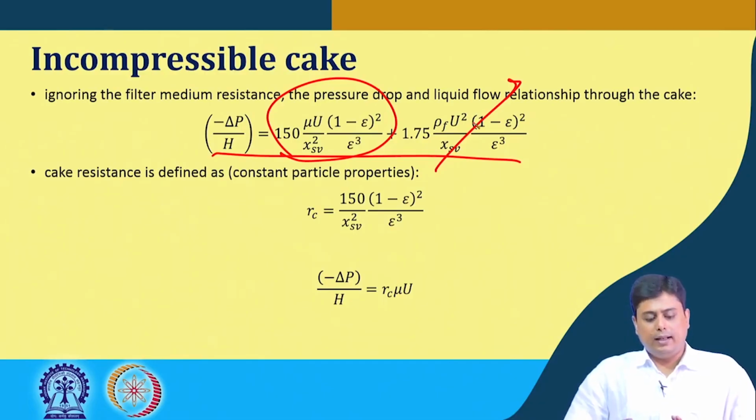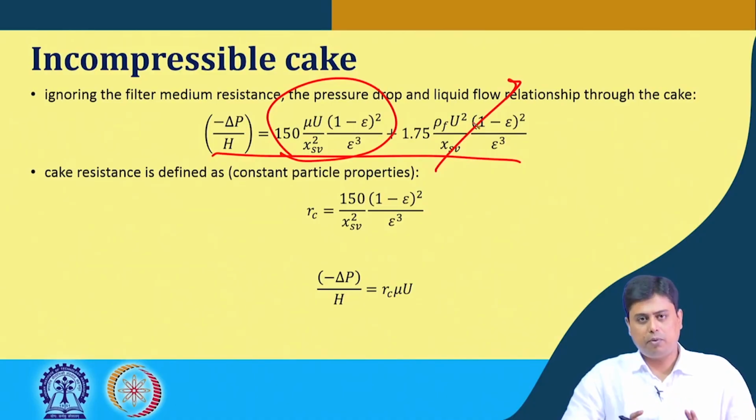Then if we consider that in that process the particle properties are constant, which means the voidage does not vary with time and the particle size is not changing with time. On an industrial scale, you can understand that tons of barrels of liquid are handled at a time, so there is a huge pressure drop required to pass this fluid through a filter media.